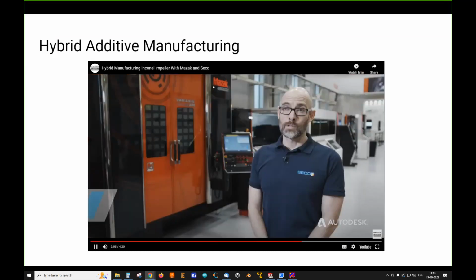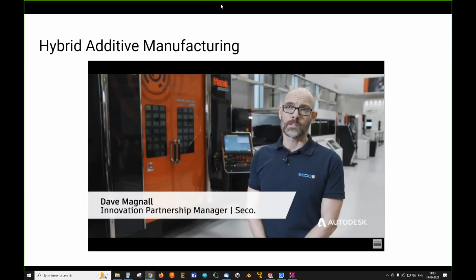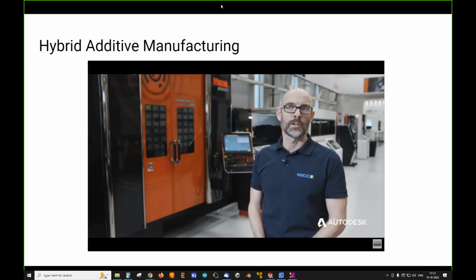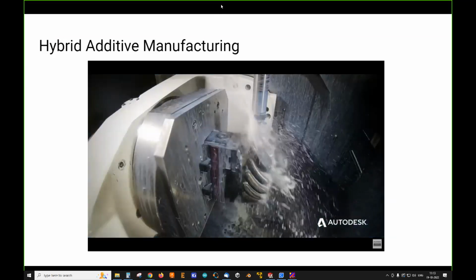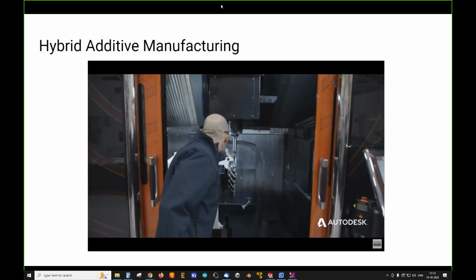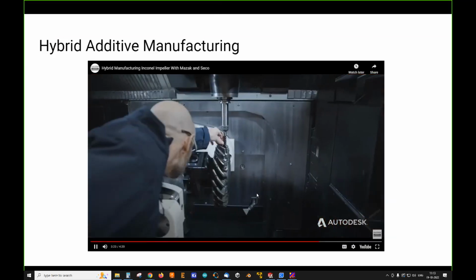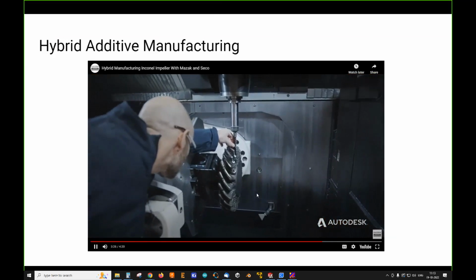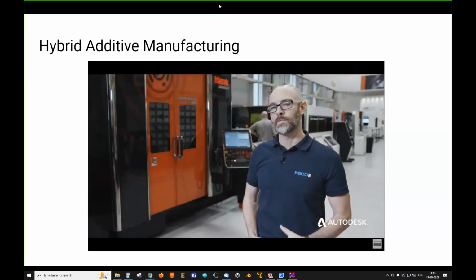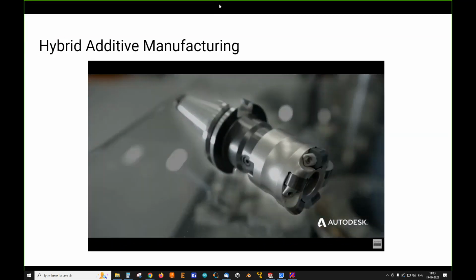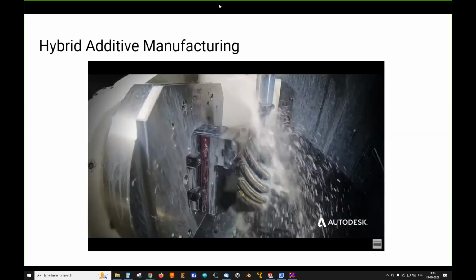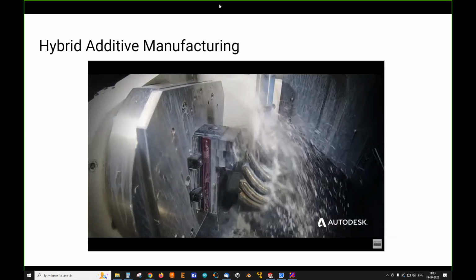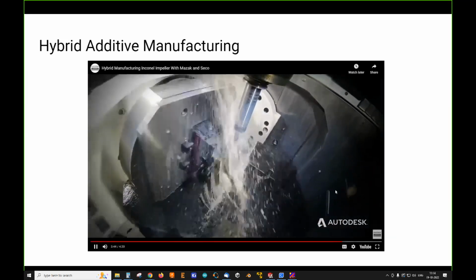So hybrid manufacturing is coming more and more to the fore, and it's something as a subtractive manufacturer we could have shied away from, but we've actually embraced. And seeing this technology emerge in the market has influenced the design of our tooling. On this demonstration, we have a combination of some of our solid carbide offering, and in preparation of this demonstration, also some of our advanced material tooling, essentially ceramic inserts. So we've looked at putting tools on there that offer great tool life and stability and resistant to damage caused by the rough surface, whilst also still offering productivity and stability.